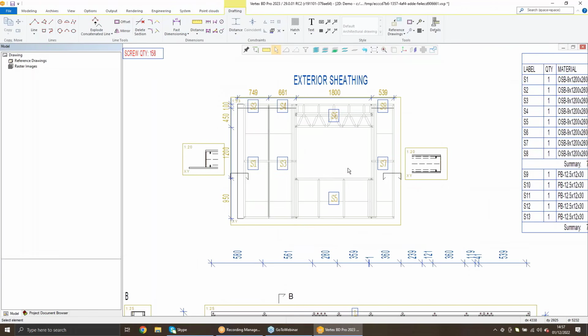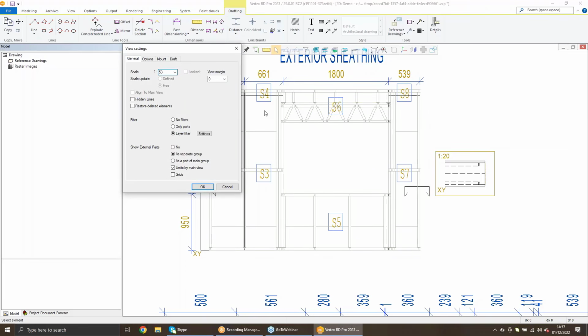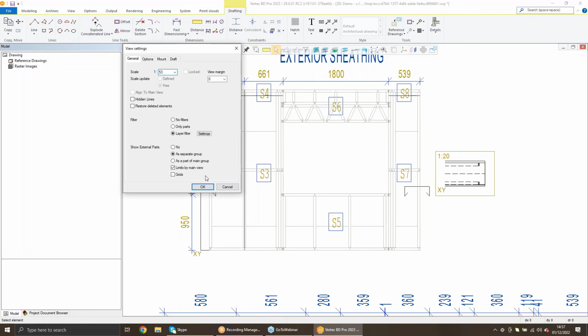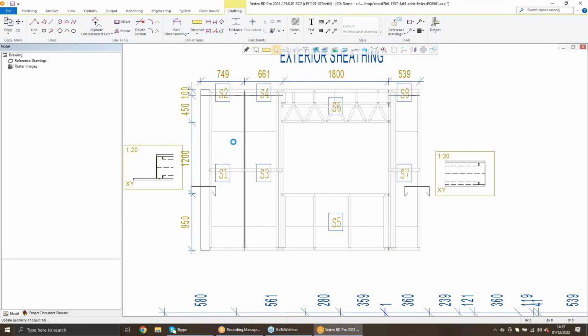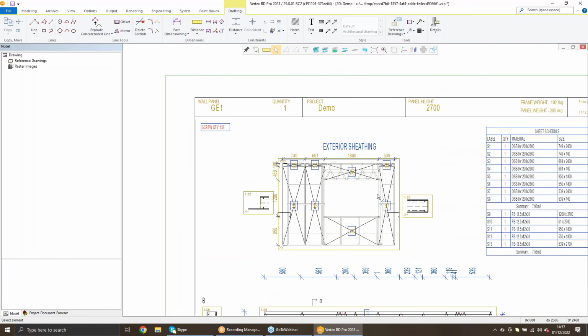And also, if you have your sheeting layouts in the templates now, I've made the core layer into a 3D reference, as it's using this new reference part line property, which makes it like a 0.1 line thickness. Let's just change that to 2D. So I think the drawings are a lot clearer now, how they go in relation to the board to the frame. That's working quite nice too.